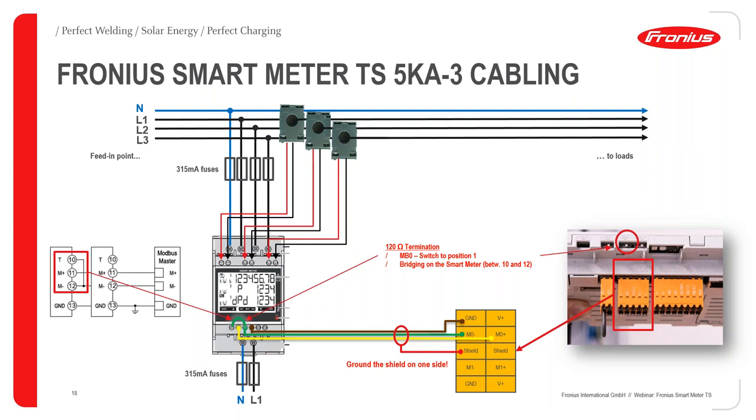Yeah, when we come to the data communication, of course, it's very similar. Again, we have the 3 connection points here, and then the bridging for the 120 ohm resistor. And also on the Gen24 inverter, of course, it's the same regarding the resistor here.